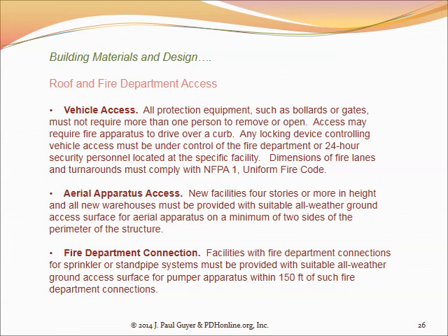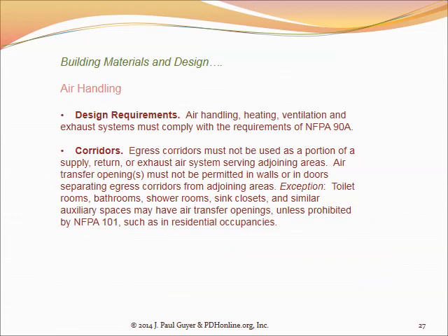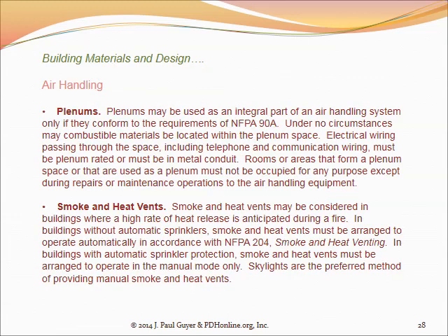Let's see. We talked about the primary challenge with the air conditioning system, and that is that left to its own devices, an air conditioning system will be blowing the smoke from where it's generated in the building all over the building very quickly, and that is a major life safety threat for the occupants.